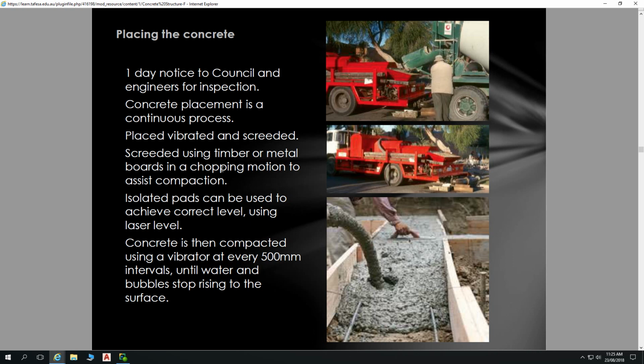But when concrete is not vibrated down properly, you get air pockets in there. Those air pockets make that concrete much weaker, because they're points where there's little support and less compressive strength, and also maybe places for termites to live, etc.